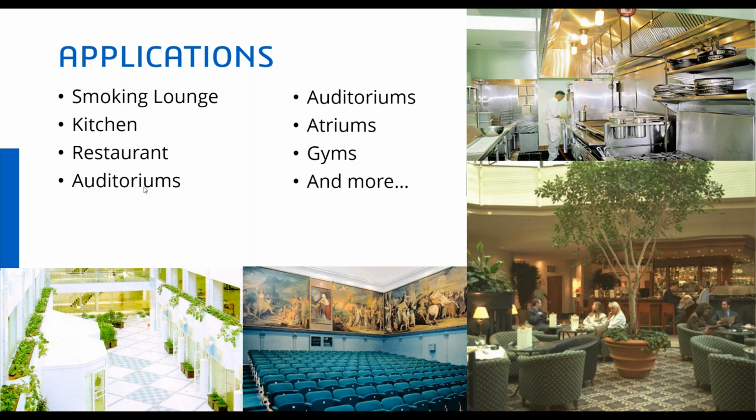So large spaces where you don't have a lot of walls or structures that are going to be blocking the airflow are perfect for displacement. So lobbies, foyers, any large waiting space is perfect for displacement.